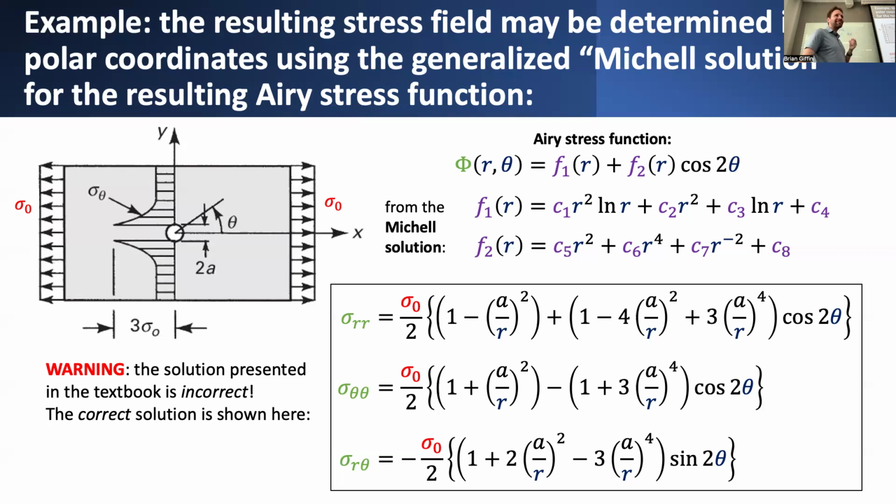It can be used in any situation. And in fact, the Mitchell solution applies to any plane stress problem. It applies even to that kind of concentrated load problem as well. The solution ends up being a subset of this collection of functional forms for the Airy stress function.